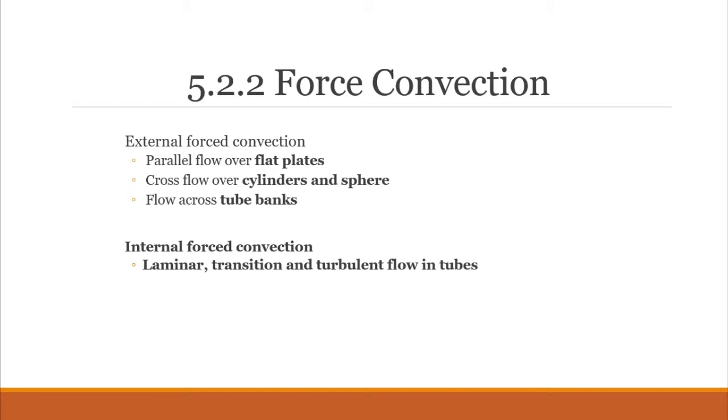There are three types of external forced convection, such as parallel flow over a plate, cross flow over cylinder and sphere, and flow across tube bank. And internal forced convection is laminar, transition and turbulent flow in the tube.